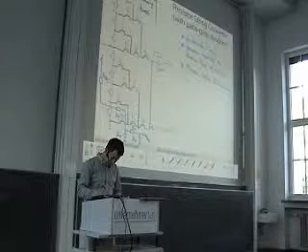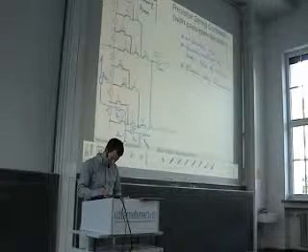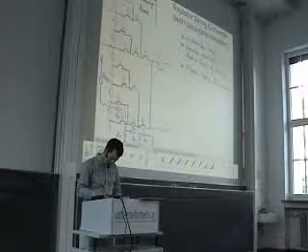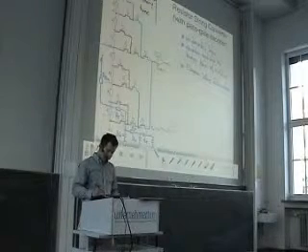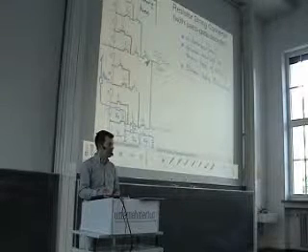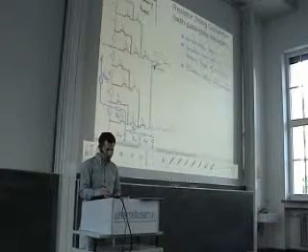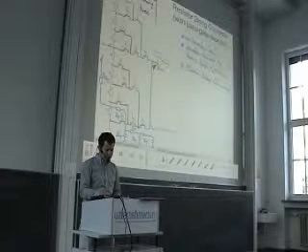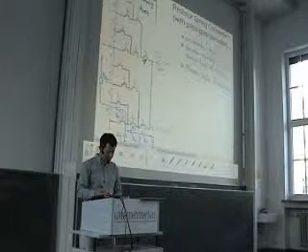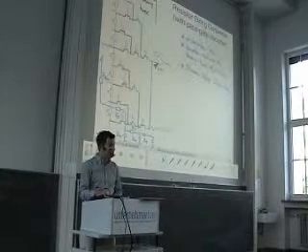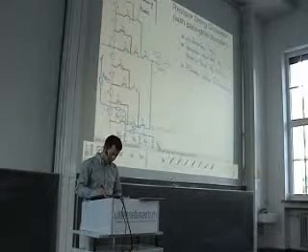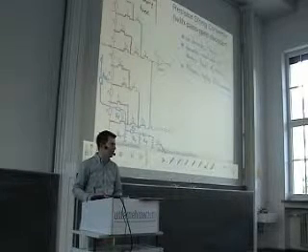Another parasitic on resistance RT. And here again we have a parasitic resistance. At this node we have only this transistor and this transistor connected. However, we have also the input capacitance into this buffer, so we have the parasitic capacitance of this transistor and the input transistor of the diff pair of the buffer. So we can say also 3 CT. This simplifies the calculation.